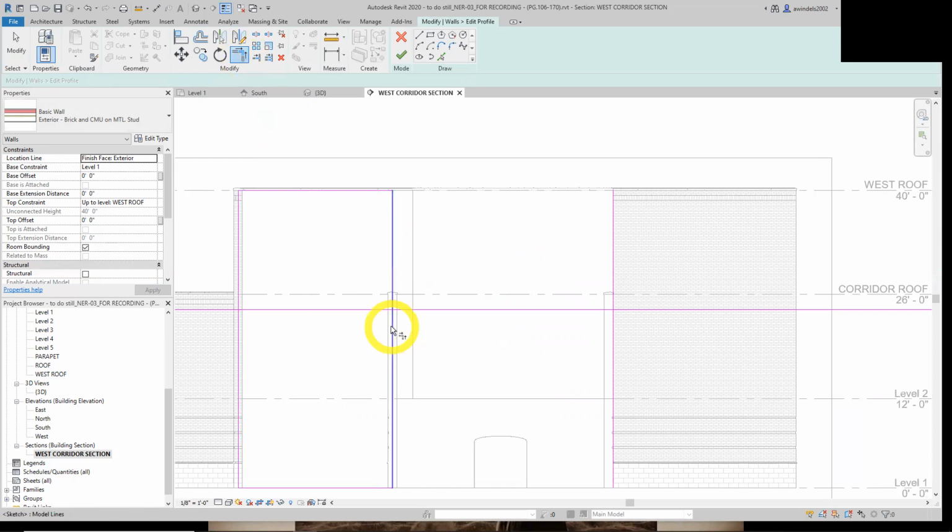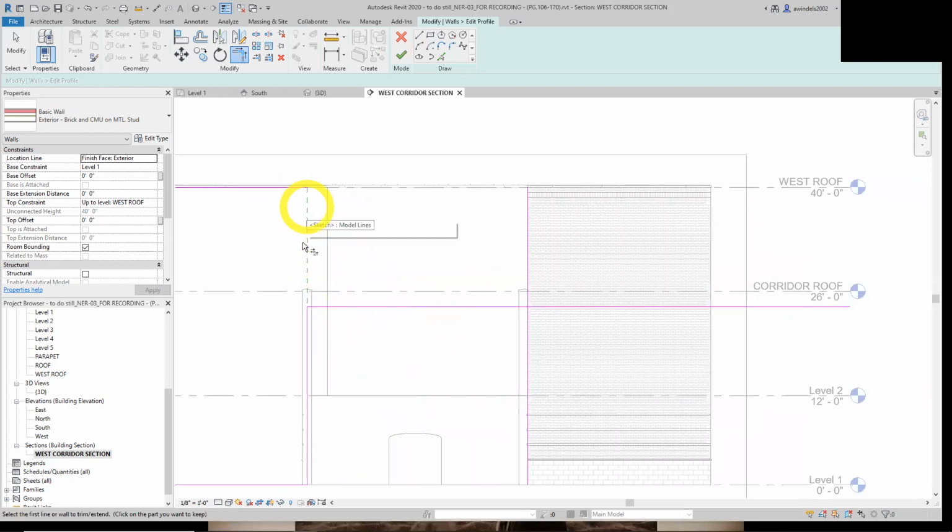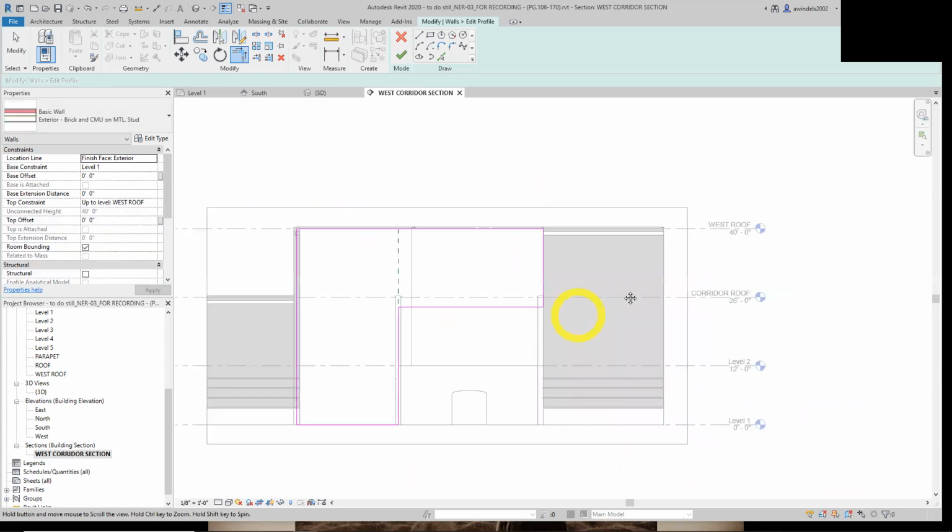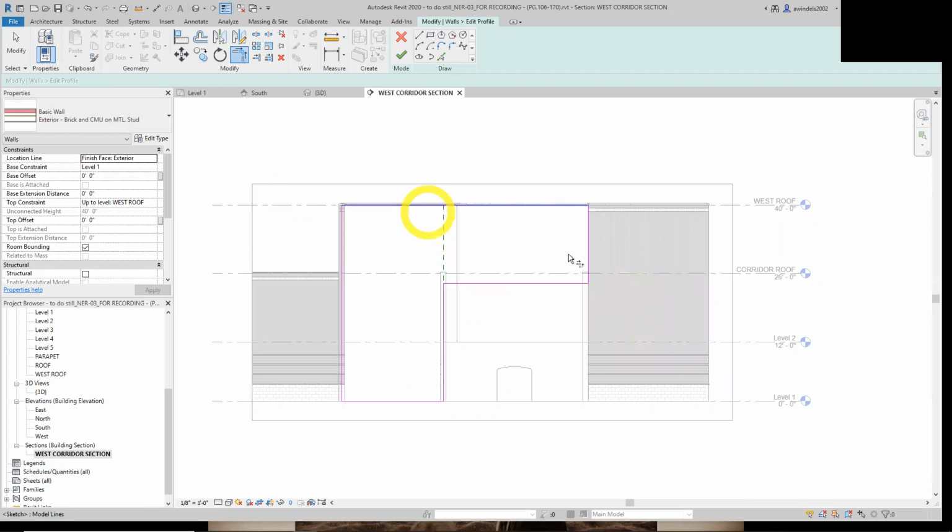Clicking the lines we want to keep. So I've had success with this working right away most times. There, it trimmed it off. There we go. I don't know why it didn't do it the first time. There's a little bit to these sketch commands. They take some practice. 5, 6, there. That's the shape we want. We want it to look closed like this. So it's one full closed shape. It works best that way.